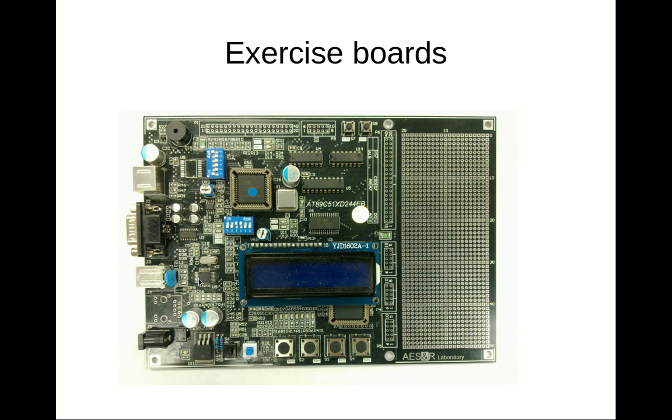And this is this little thing here, what you see. This is a so-called FTDI chip, and it is used here to translate these signals into, so to speak, the native serial bus of our microcontroller. I should also mention here, this microcontroller is not only the CPU, but already has many peripherals like memory, EEPROM, the programming memory, the RAM, all these things integrated into this chip alone.